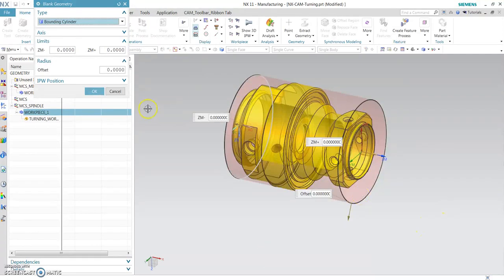You can select the stock where you want on the Z, the front end of the part model. You need to use a facing tool to do a clean cut, and for the backside stock, you need to give 1 millimeter for once you do all the front op, part transfer, cut off, part transfer, and do the operations on the second spindle. We need some face for second side cleanup.